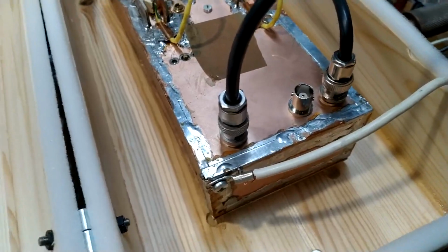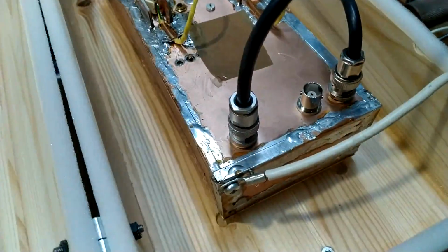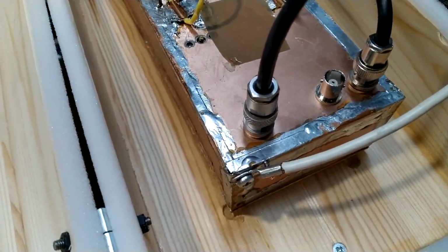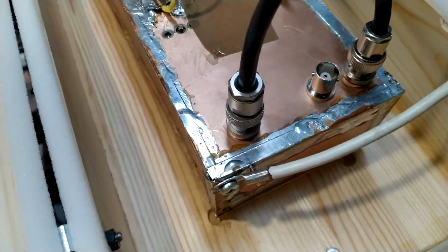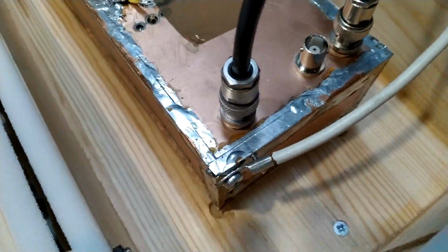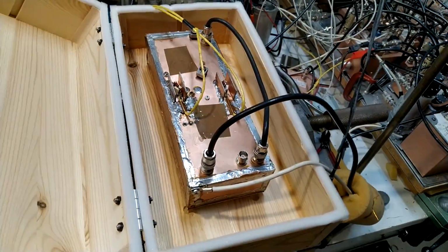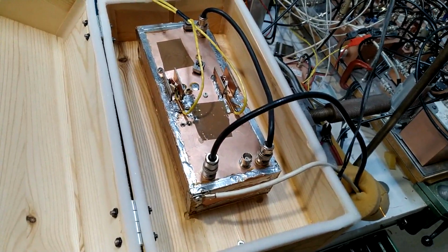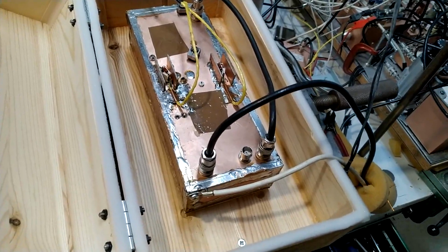The only connector I have moved when moving the box inside here is this one, the output connector. I had a T connector inserted in between before to make the box a little bit lower, but that's not needed anymore. So I have cleaned this and it didn't make any difference at all. I have added a fan to blow a room temperature air stream onto the oscillator, because now when it is in the box, air circulation is not at all as good as it was before, and that means that the temperature has become higher while it is in this position.